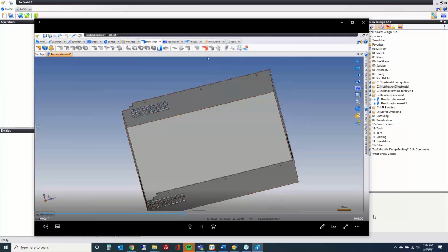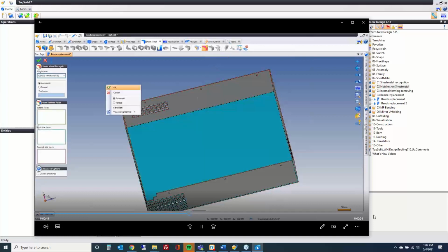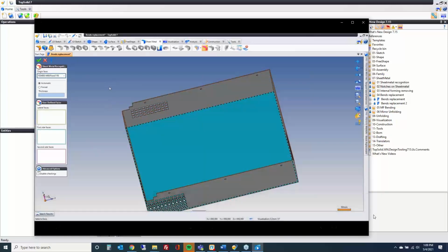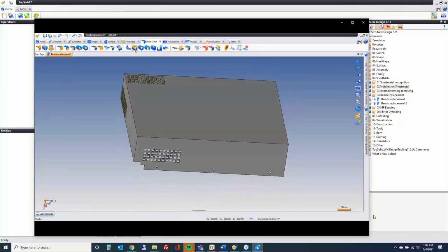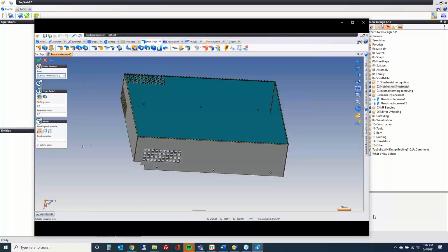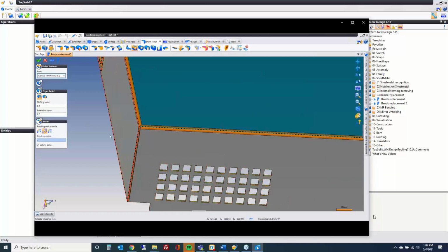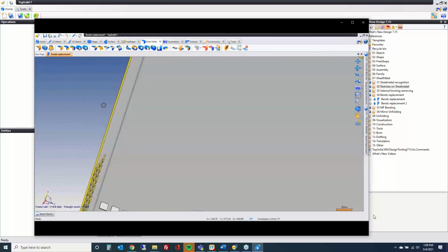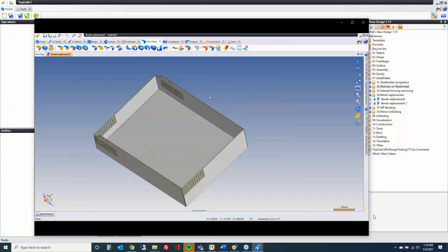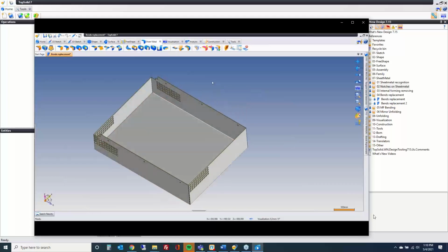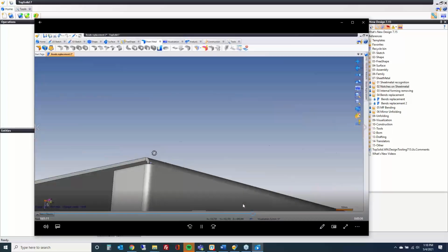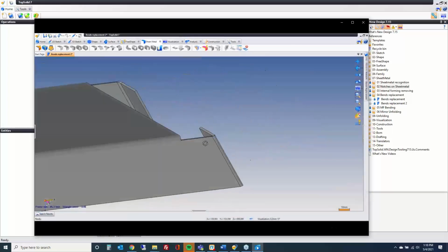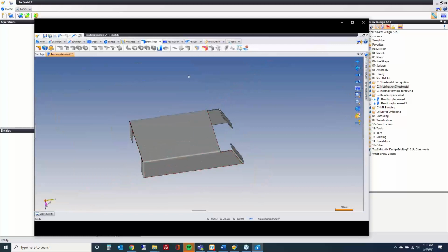And then from there, we can go ahead and recognize the sheet metal part. And then we can go put reliefs back in. So we'll say we want to process that face, have it put the right bend radius in, put the right reliefs in, and off you go. So again, it's just a tool to help simplify the process of importing parts and correcting things that are not designed properly. Okay, so here's another sample.